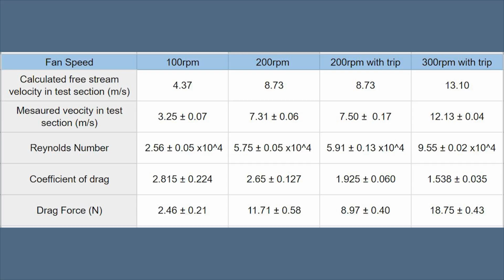We also verified a reduction in drag due to turbulent boundary layer effects through the use of the trip strip. This relates to strakes, which are used on real-life structures to break up vortices and diminish the frequency at which they shed. This is important because vortex shedding can cause catastrophic instability if the vortex shedding matches the harmonic mode of the structure, causing further excitation.